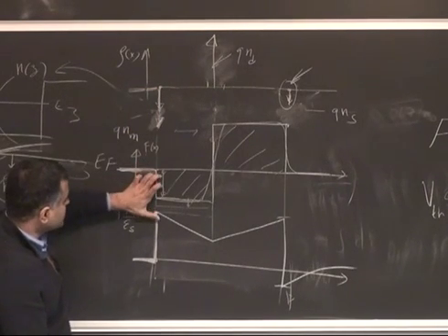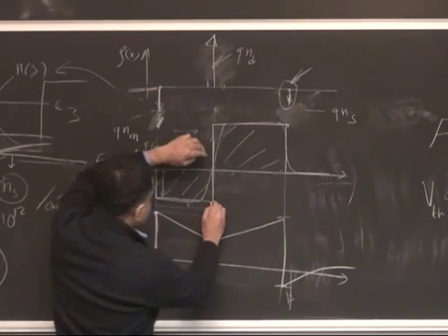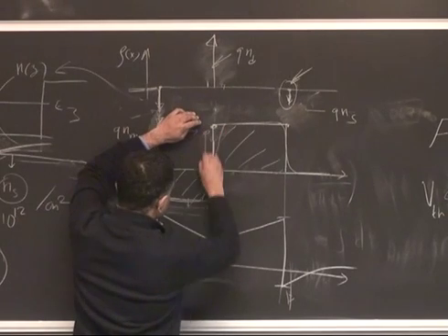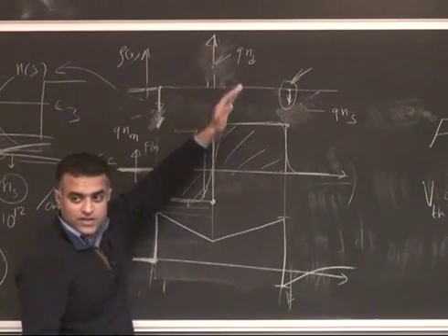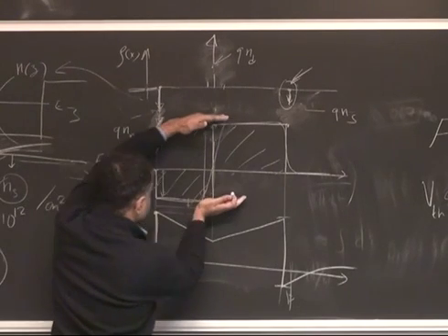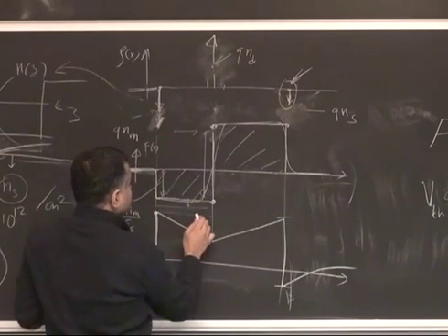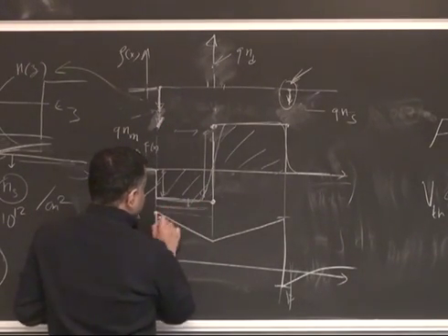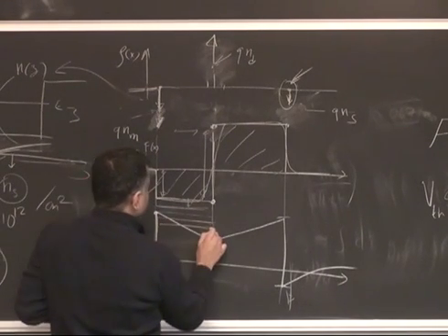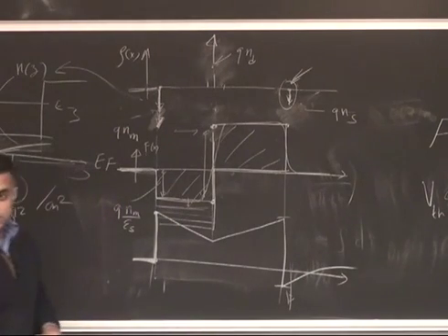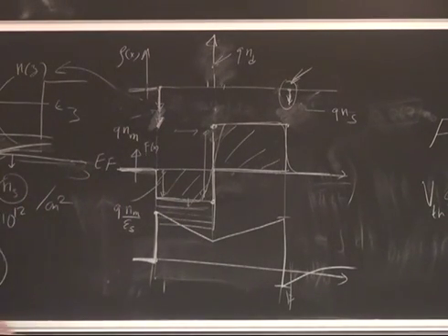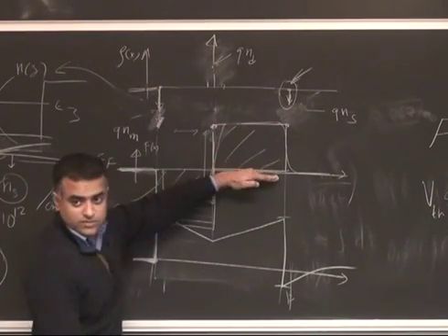So this is going to increase, but then the difference between these two points cannot change. Why? Because this thing is not changing. Stuck, right? So the whole thing essentially just gets pushed down, and you can see right away that there will be a critical field or critical voltage at which the field in this region will vanish. It will go to 0, right? Because the whole thing is going down. At some point, the field here goes away.